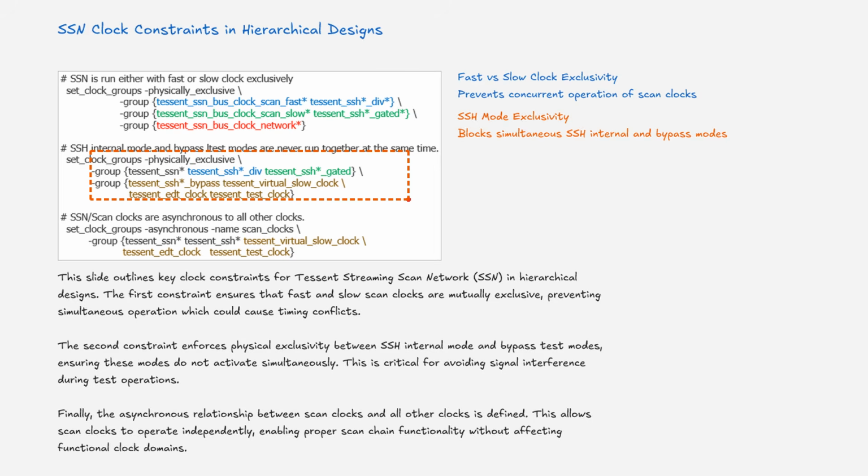activate simultaneously. This is critical for avoiding signal interference during test operations. Finally, the asynchronous relationship between scan clocks and all other clocks is defined. This allows scan clocks to operate independently, enabling proper scan chain functionality without affecting functional clock domains.